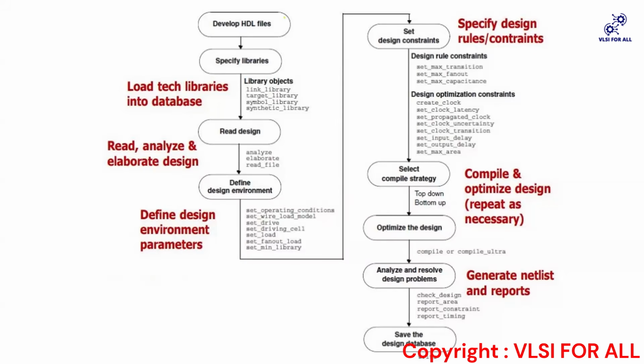So I will define what DesignWare components are. DesignWare components are already pre-optimized for PPA purposes, that is, for power, performance, and area. So it replaces HDL arithmetic operators in the code with DesignWare components. That is the definition of elaboration.